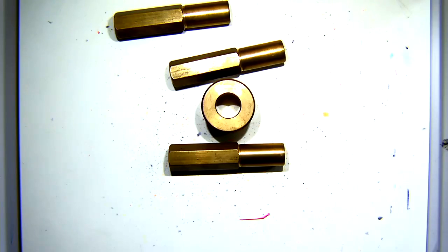Those rectangles, the tolerance height, which way do we go? Where do we put most of our tolerance? Where do we put less of our tolerance? If you've got the facilities to do one versus the other, that's the sort of thing you do. The standard issue approach for most of this kind of mechanical, automotive size, aircraft size manufacture is we have tighter tolerances, or smaller rectangles, for the shafts than we do for the holes.